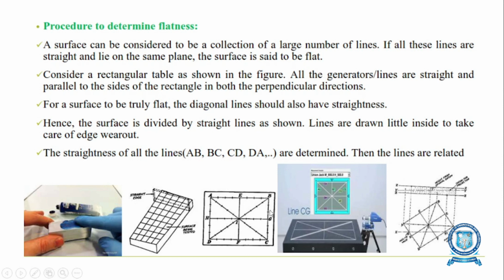The positions H and G, E and F are the known positions of the value. So it is now possible to fit in lines HG and EF. It also provides a check on previous evaluations, since the midpoint of these lines should coincide with the known position of midpoint I. In this way, the height of all points on the surface relative to the arbitrary plane ABD is known.